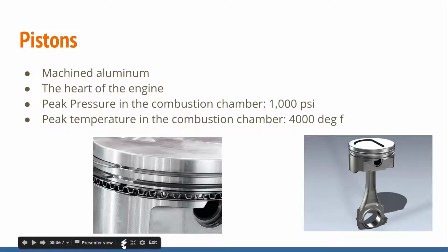Some kind of interesting information here. The peak pressure in your combustion chamber. So when that spark plug fires your air-fuel mixture, you're actually going to get 1,000 psi of pressure inside that combustion chamber. Peak temperature inside the combustion chamber, 4,000 degrees Fahrenheit. So there's some serious amount of pressure and heat inside that combustion chamber. So your pistons really put up with a lot of abuse. And they're always aluminum.